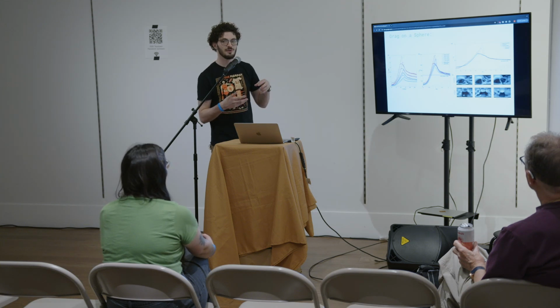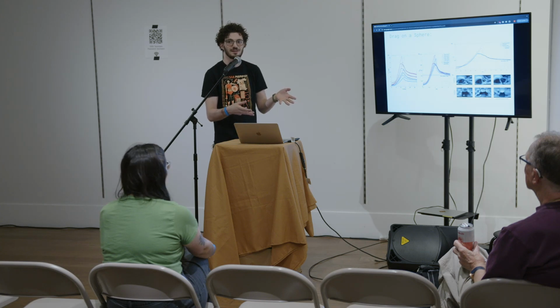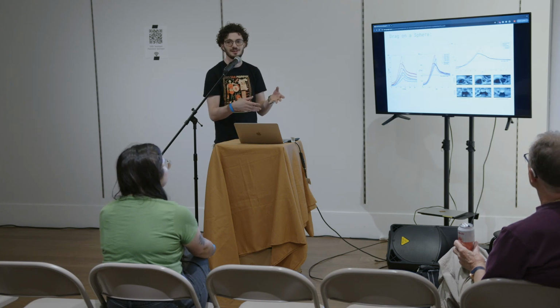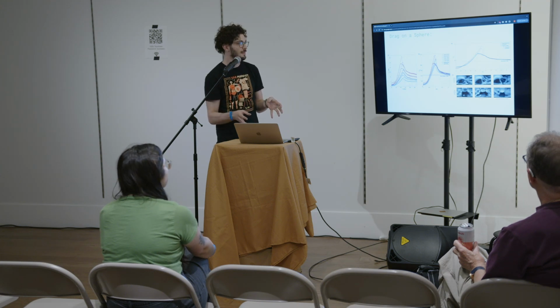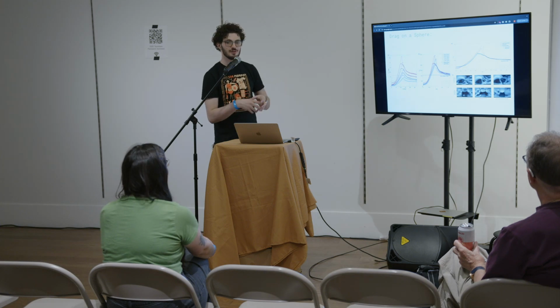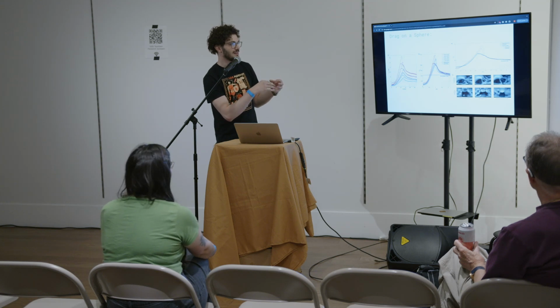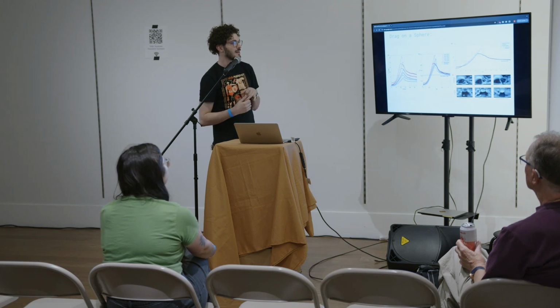The thing that none of the theories that we looked at explain is this huge peak before we get there. So you might think that when the sphere is partially submerged, you have part of the drag. Like if it's half of the area, then you get half of the drag. And that's sort of what happens at some scales, but at this scale, it's not at all what happens. You get this huge peak that can be 3 or 4 times the free stream drag because of the deformation of the water, because of the wake and the way the water builds up in front of the object and adds this extra pressure onto the object.